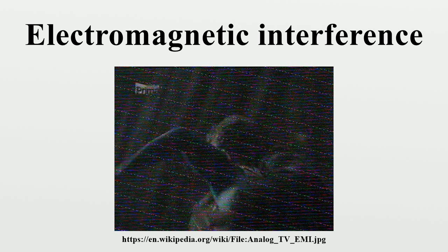A common technique to deal with RFI within the observed frequency bandwidth is to employ RFI detection in software. Such software can find samples in time, frequency or time-frequency space that are contaminated by an interfering source. These samples are subsequently ignored in further analysis of the observed data. This process is often referred to as data flagging. Because most transmitters have a small bandwidth and are not continuously present, such as lightning or Citizens band radio devices, most of the data remains available for the astronomical analysis. However, data flagging cannot solve issues with continuous broadband transmitters, such as windmills, digital video or digital audio transmitters.